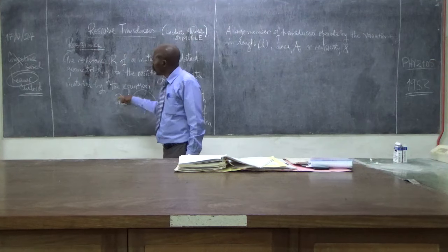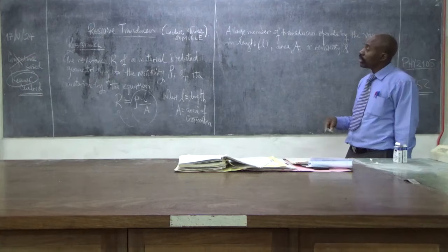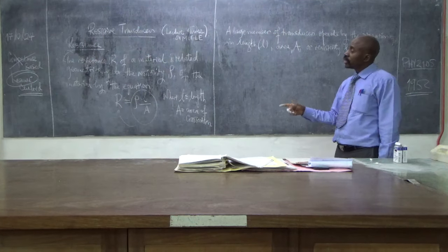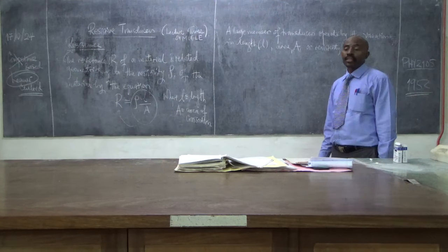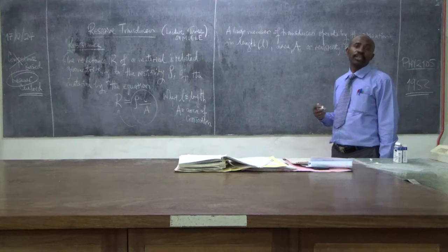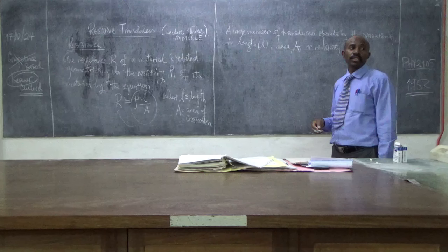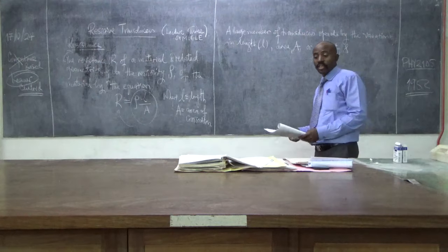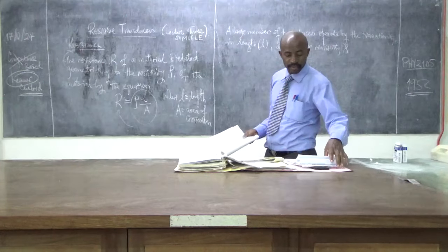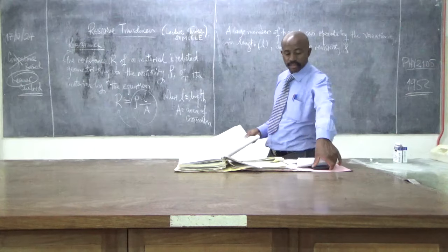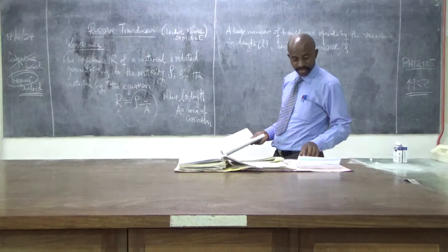And once your sensor depends on the resistance, like if you integrated your resistance in the AC deflection bridge, then that part of the resistance will be changing in the bridge, and then the voltage will be changing. When that voltage changes, your sensor works, and you will be able to determine what is going on.